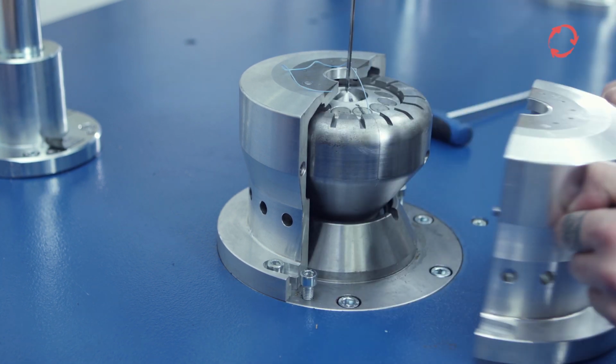The mandrel is then rotated such that 2 magnets are visible on the left side between the narrow side of the mandrel and the housing. The angle should be around 45 degrees. Now it's time to make a color marking. The color marking ensures the correct positioning of the mandrel and helps to avoid problems during the working process.